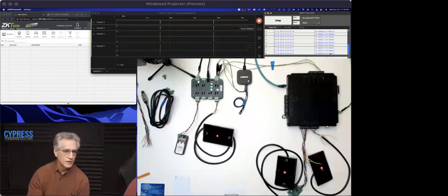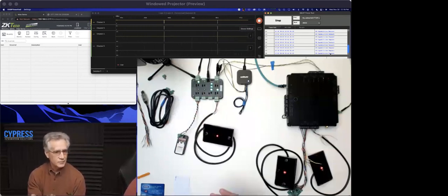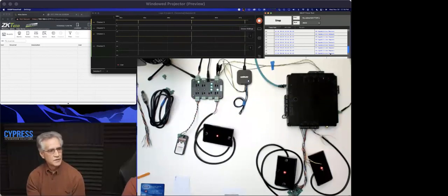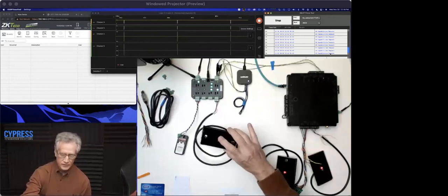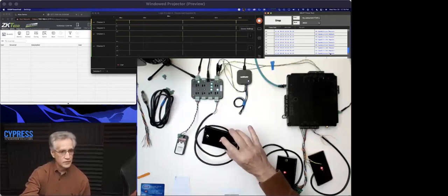So by looking at this, right now you would say, well, I really don't know what's going on. You could send this trace, or at least describe what you're seeing, to an expert back at the mothership, so to speak, and they would be able to say, oh, well, it's polling, it's looking for address 0, and it's not finding it.